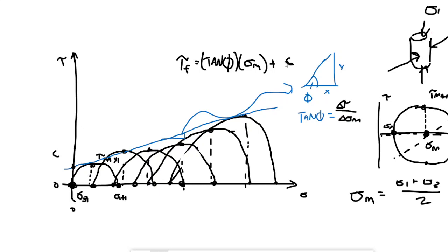Again, it's not particularly practical to have a case where you're going to be worried about the cohesion causing you failure because you're in an unstressed environment. But it is a property of rocks that we can test for and record and then use in subsequent modeling. So that's why we really care about it. So there it is. That is a linear equation. That is the Mohr-Coulomb failure criterion for shear failure. And again, thinking of it exclusively in terms of compressive stresses is a little bit dangerous.